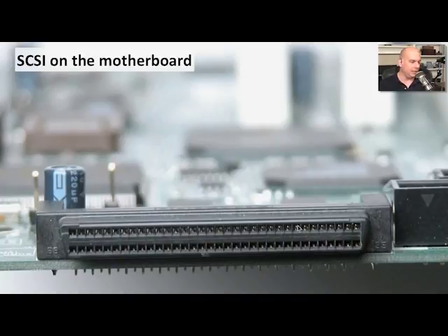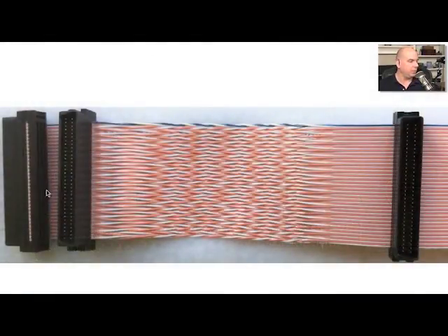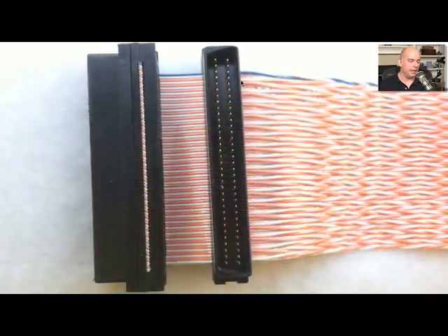This SCSI connection has quite a number of pins associated with it. The cable that we would use to connect this would be something like this, where we would plug into the motherboard, and then there might be many different connections on that same cable where we could use all of these different SCSI devices and plug them all in at the same time. If we were to look closer, you can really see a lot of different pins being used. And on this particular SCSI connection, it was a higher bandwidth, so it needed a lot more pins to be able to communicate.